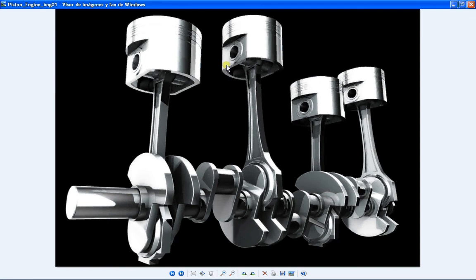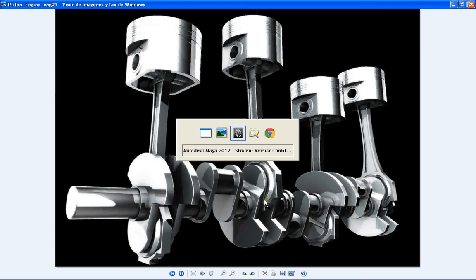We're going to create a couple circles here for the top of the piece, another one for the bottom. We're going to do a couple booleans to make this cut, this interior cut. We're going to use a combination of NURBS surface and a little bit of polygons. We'll see afterwards. We're going to create also the reference lines. We're going to create this outer circle, this vertical line, and another circle here, and of course the circle for the extrusion of the main piece in the axis. Okay, let's start with it.